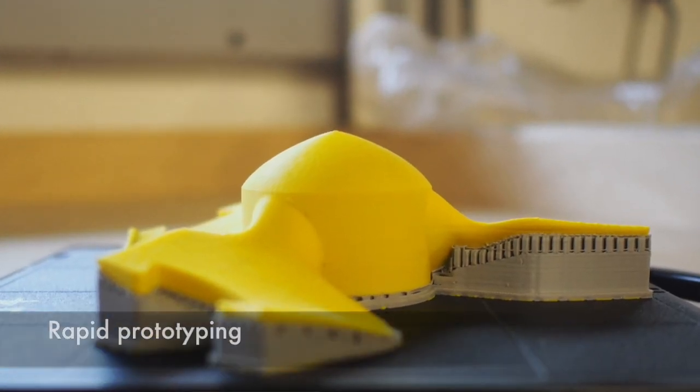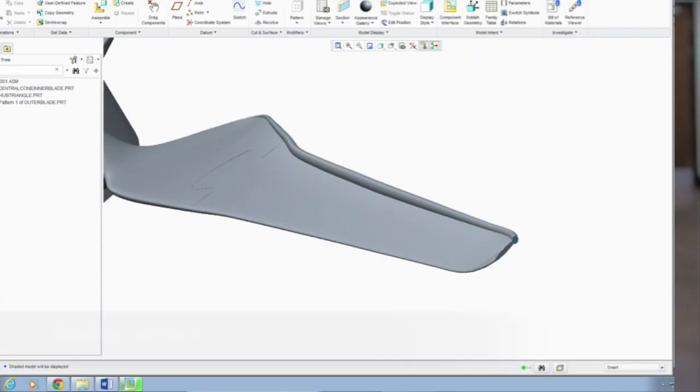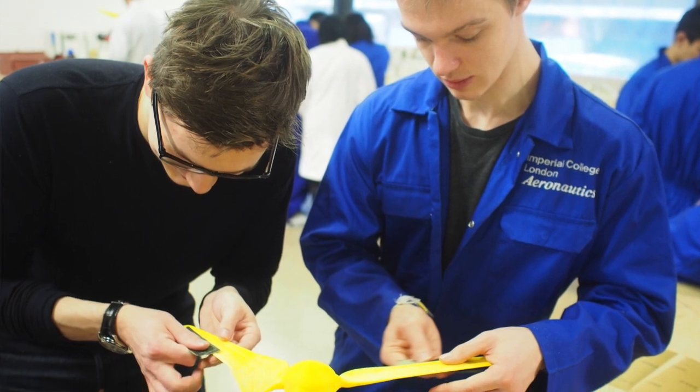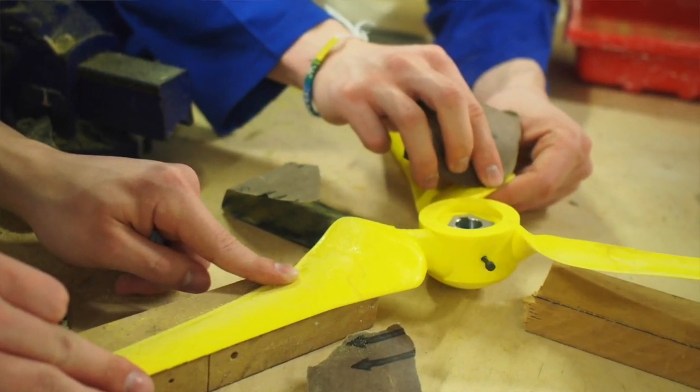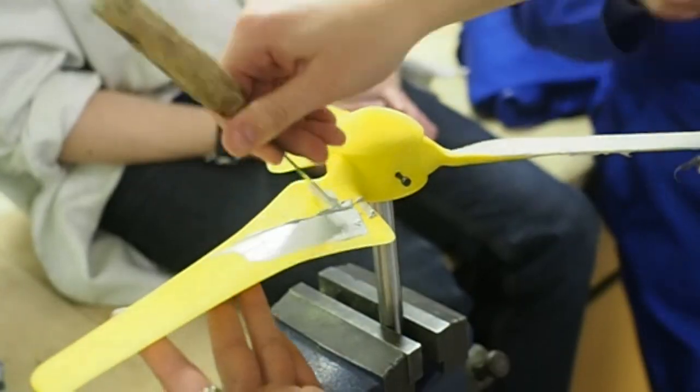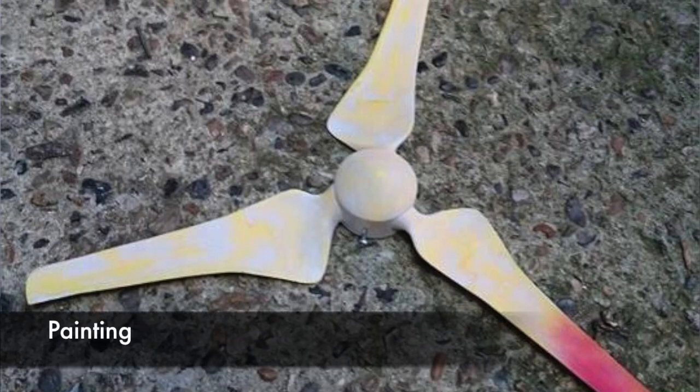Rapid prototyping was used to make the turbine parts from ABS plastic, and these were glued together. Due to printing limitations, the trailing edges had to be artificially thickened and later sanded to the correct shape. Modelling filler was applied to mask surface imperfections and ensure that the model was not deformed too much during sanding. The sanded model was then spray painted for a smoother, more attractive finish.